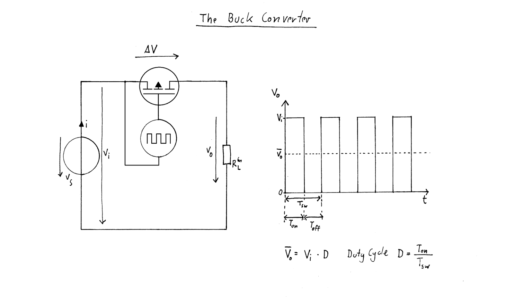Now, of course, you will think, alright, so by switching the transistor on and off, I can control the mean value of the voltage across the load. But that mean value is just a theoretical value, while in reality the voltage across the load is not constant, but just periodically jumping from zero to the input voltage. That is right, and sensitive electronic equipment cannot be supplied with such a pulse width modulated voltage directly.